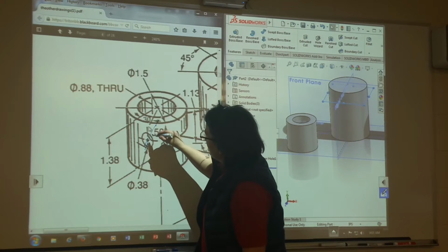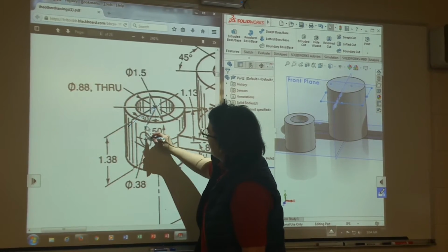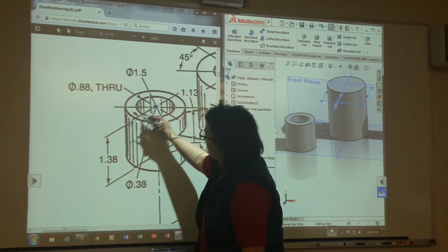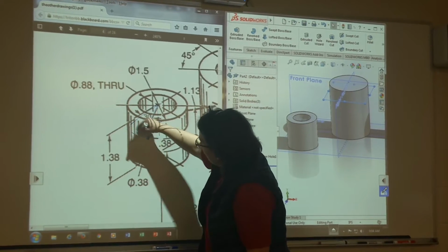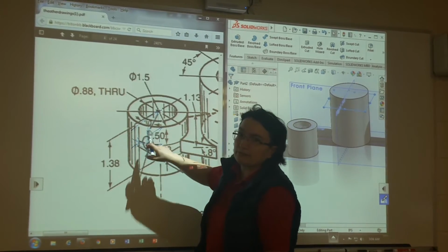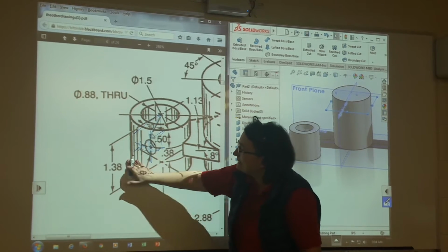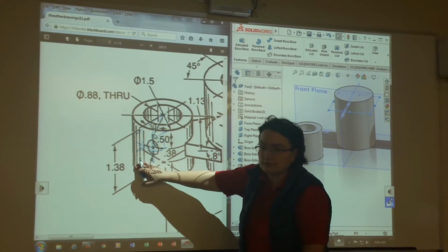In order to drill this hole, as I talked about before, you have this angle and this angle, which is correlated to this position down here. I need to know this location, and I need to know this location. These two locations I must have. If I don't have these locations, I can't drill that hole. I cannot pick the face of this object because it's curved.